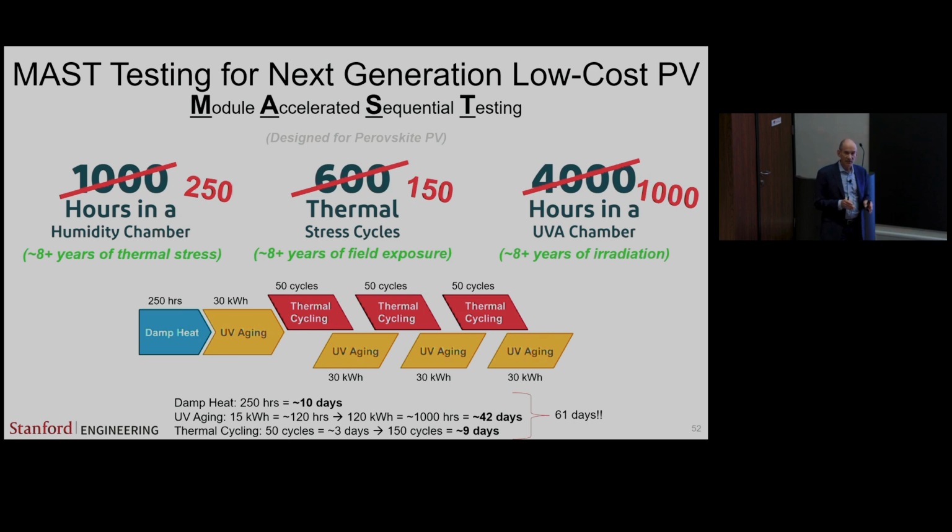What we find there, with very sophisticated modeling that we're doing, is that there are very complex synergistic effects where some degradation mechanism that might be happening in the EVA encapsulation material used in the silicon module is producing acetic acid, which is diffusing somewhere, causing a corrosion product on a line, which is causing a gas bubble to form, which is causing delamination. Those kinds of things you really only see when the technology starts to mature more.